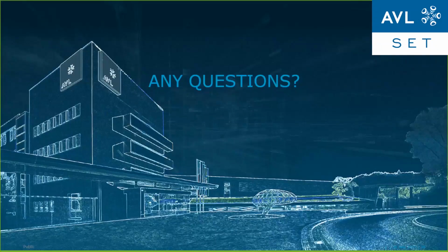Can we test an inverter with a power rating which is higher than the battery emulator? For example, the inverter has 250 kilowatts and the battery emulator has just 160 kilowatts. No, this is not possible. It always needs to be taken care that the battery emulator power capacity has to be considered. So even if the inverter is capable of handling more power, the safety limit now comes from the battery emulator itself.